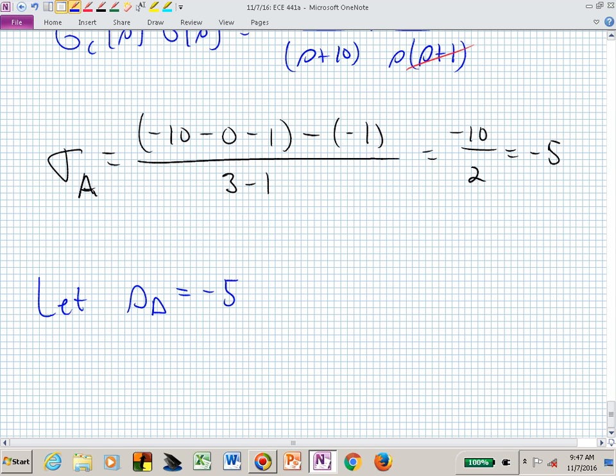Well, if we haven't yet, we will start learning that this 45-degree angle is sweet. That's 45 degrees. It's a theta of 45. It's a zeta of 0.7. It's a percent overshoot of 5. It gives you a nice speed. It gives you very little overshoot. That's just a nice value, having that 45-degree angle. So we are now looking at that for our s deltas.